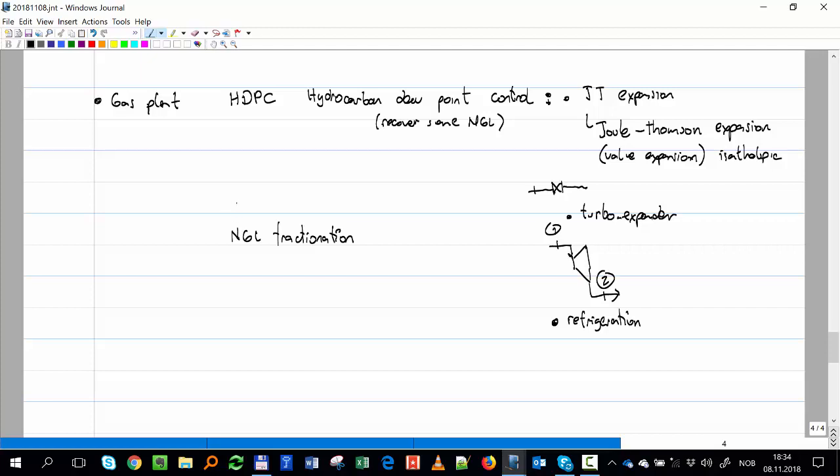Well, before that we have the demethanizer, and NGL fractionation, which basically is a process like a distillation tower, where I have different trays with different temperatures, and at each tray where I have an output, I have the product at a certain temperature. I drain propane, butane, and so on. We are not going to talk about that too much. So, chemical engineers, you have your eyes open, you say, "Wow, I like it." We're not going to talk too much about it, petroleum engineers, but just to make you aware of that.